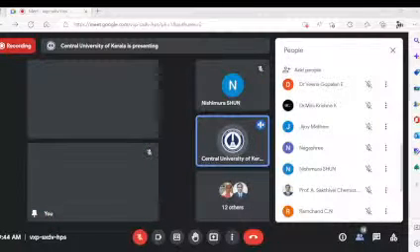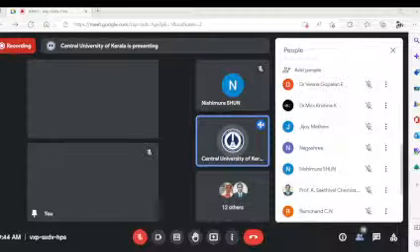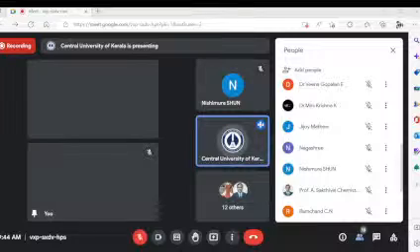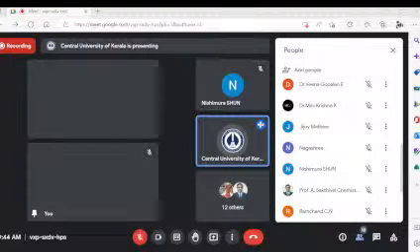On the left side you have the Seebeck effect, and on the right side of this viewgraph you have an example for the Peltier effect, so thermoelectric cooling. So let us move ahead. Now this is what it is from a physics point of view. I have simplified it. One Seebeck device couple consists of one N-type and one P-type semiconductor pellet.